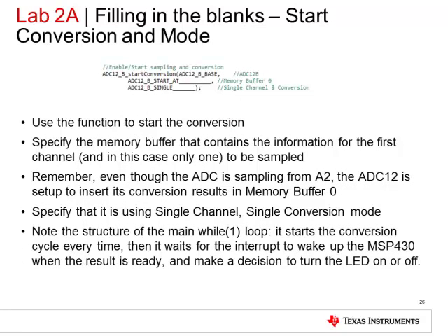Now we set up the function that triggers the start of conversion. We also need to make sure the ADC is configured to single channel, single conversion mode. Using the single conversion mode means that software will be required to set the start of conversion bit each time a sample is required. Check your settings against the solution.